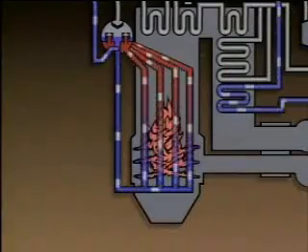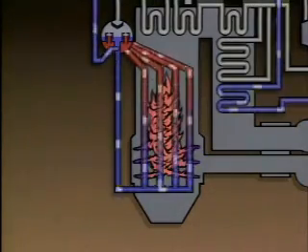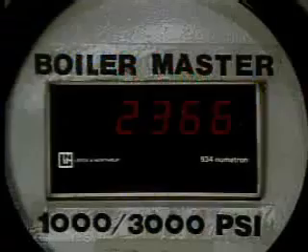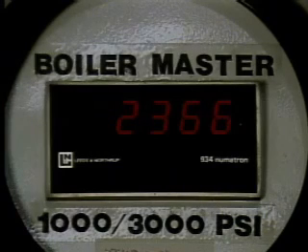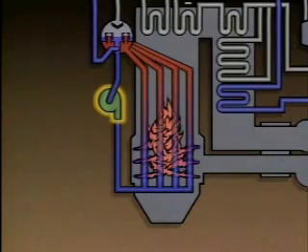The cooler water is also heated and rises, creating a self-sustaining flow through the water side of the boiler. Natural circulation of water in a boiler is affected by 2 factors. They are the amount of heat produced in the boiler furnace and the pressure at which the boiler operates. For example, raising the temperature in the boiler furnace increases natural water circulation because it results in a greater temperature difference between the water walls and the downcomers. Increasing the second factor, pressure, has a negative effect on natural circulation because as pressure increases, the density difference between water and steam decreases.